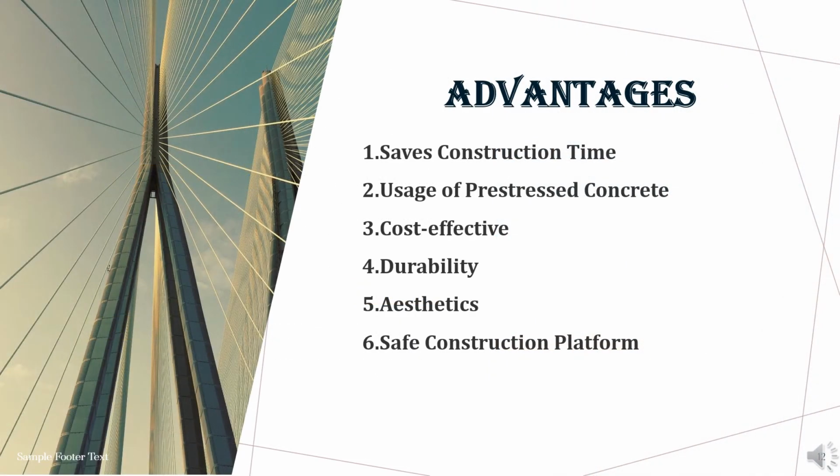There are many advantages of precast concrete. Saves construction time. Precast concrete construction saves time. The risk of project delay is also less. The precast concrete casting can be carried on simultaneously with other works on site such as earthwork, survey, etc. and thus saves time. Quality assurance. The key factors which regulate the quality of construction such as curing, temperature, mix design, formwork, etc. can be monitored for precast concrete. So, improved quality construction can be performed.